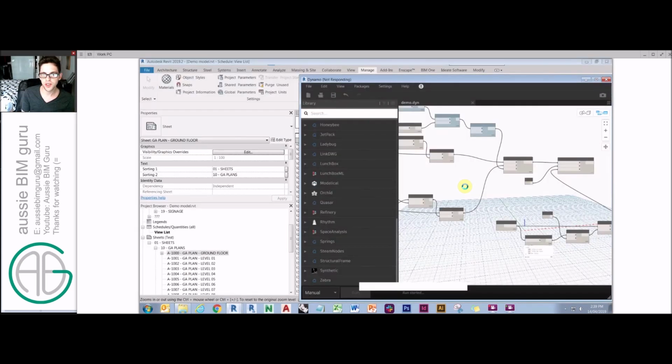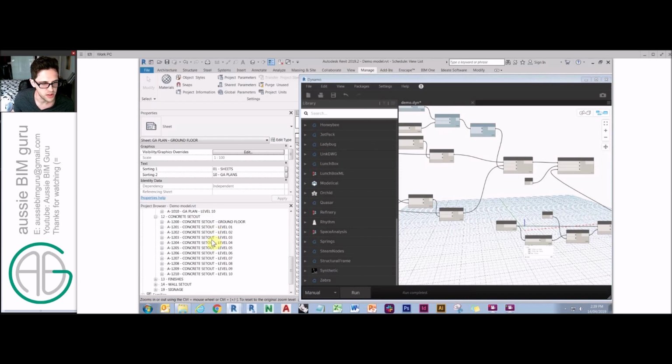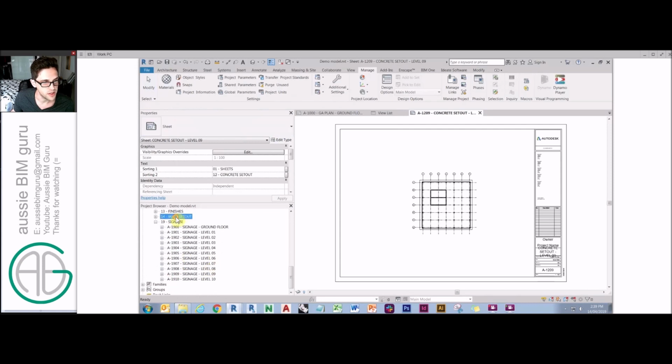It shouldn't have to generate the sheets themselves, so you shouldn't have to worry about the graphics reloading for each of these. But overall, you can expect it to take maybe about 0.1 of a second per view, possibly. But you can see there it is. It's successfully placed every single view on every single sheet, and it's positioned them the exact same way as my reference sheet, and it's set its viewport type to none as well. So very powerful, saves a lot of time.